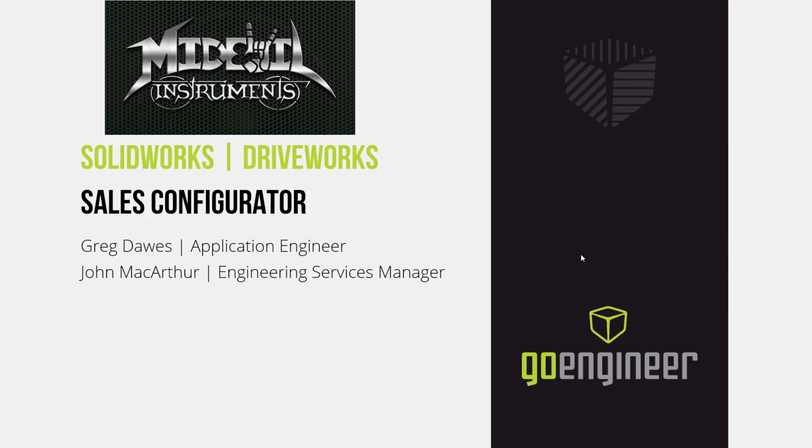In this particular case, we're not actually even calling up the CAD model and altering the configurations, and we'll get to some of the details of that as we move forward. But there is that next level where you're calling different CAD models, swapping out assemblies, sub-assemblies, and things with DriveWorks as well. You can drive dimensions with DriveWorks as you interrogate the model, to be able to create model designs that have not been created yet for sizes and things, as well as drawings, things of that nature.